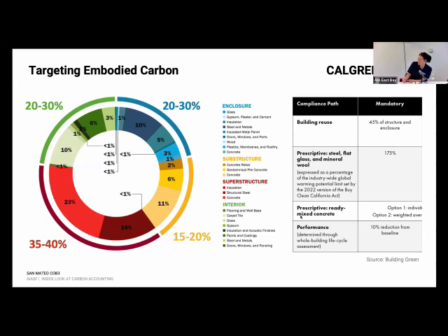I'll give you another example. Metal deck. On the West Coast, our metal deck is often made from basic oxygen furnace facilities, right? And those are higher carbon facilities than electric arc furnaces, which are all east of the Mississippi effectively. So you can get that lower carbon metal deck, no problem, but you're going to have to pay additional handling and shipping to get it to the West Coast on your job. And you can quantify the carbon savings and the premium associated with that very easily.